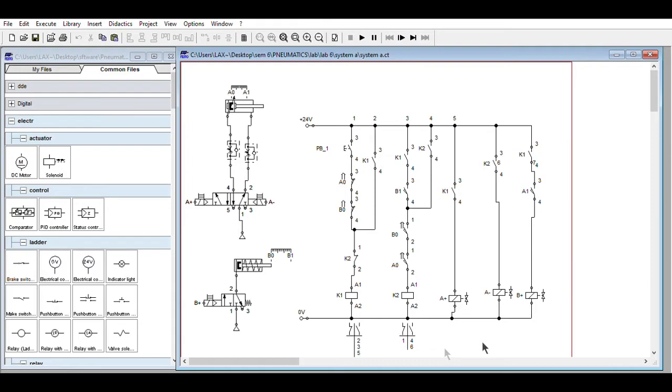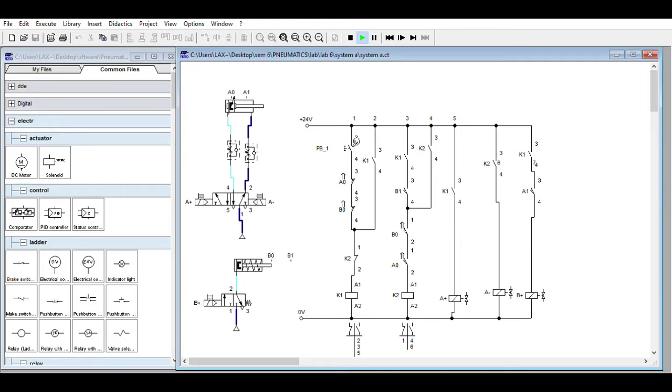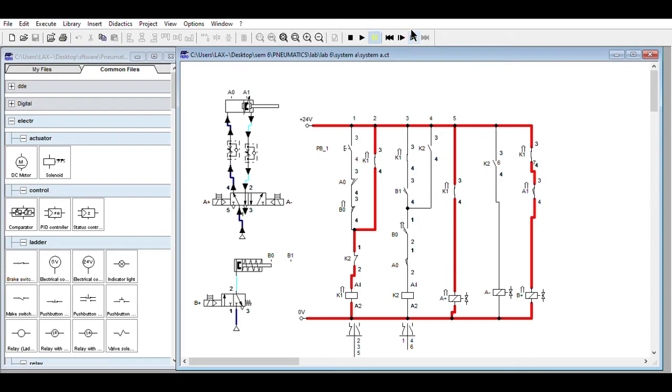The circuit is constructed following the ladder diagram we constructed earlier. When sensors A0 and B0 are on, the push button is pressed so that contact relay 1 is latching and makes cylinder A extend. When cylinder A is in the extended position, the A1 sensor and contact relay 1 signal the single acting cylinder to extend.